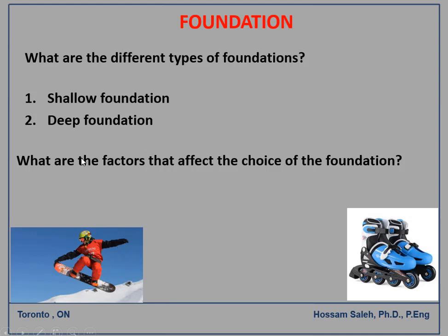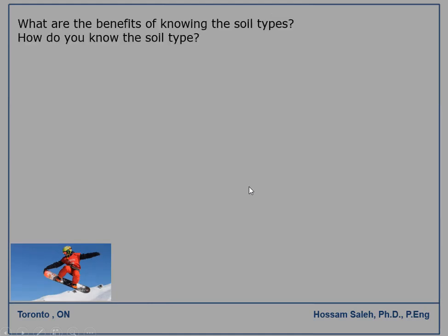So how can we decide on the type of foundation we are going to use, and what are the factors that affect that choice? It depends on many factors actually. How high is your building? Each floor has its own weight and live load, and the more floors you have, the heavier will be the load on the foundation. So it depends on the type of the building, how many floors, and the load from the building. That's one factor. The other factor is the soil.